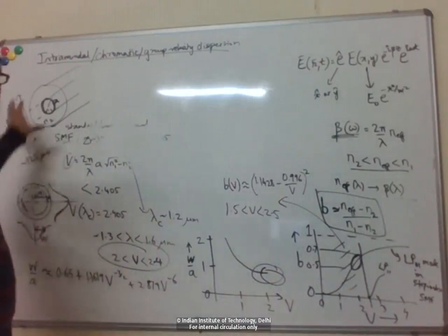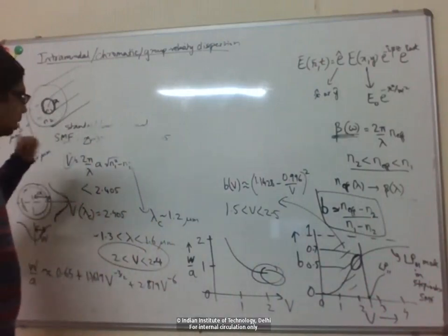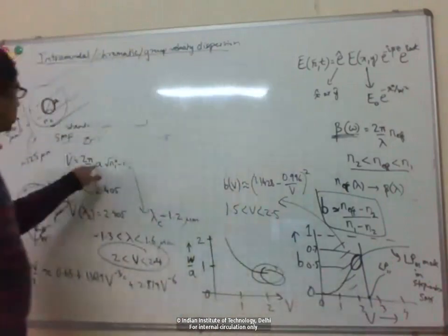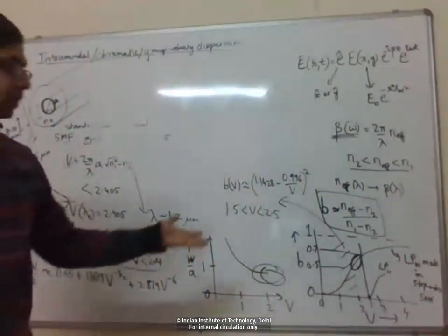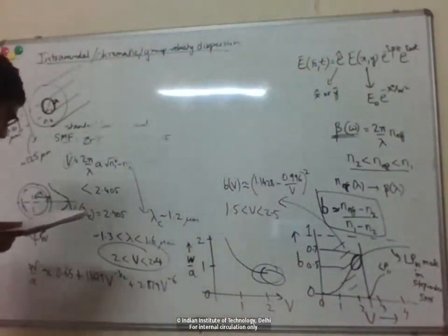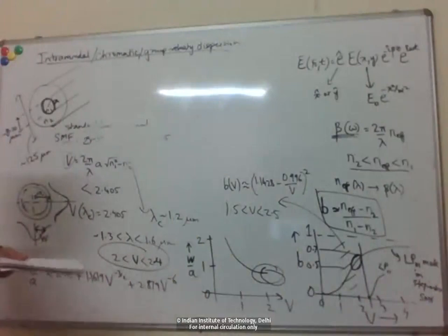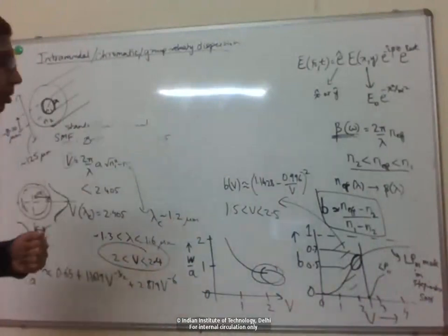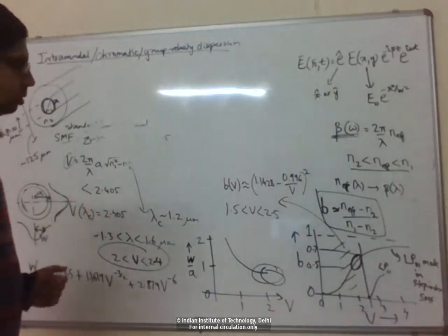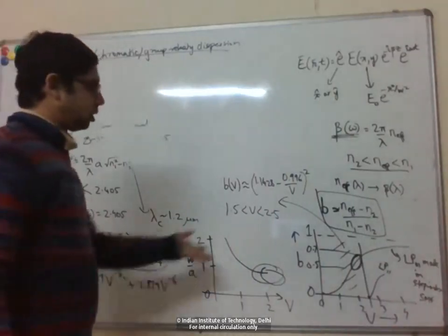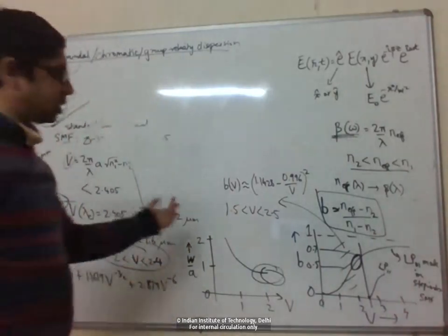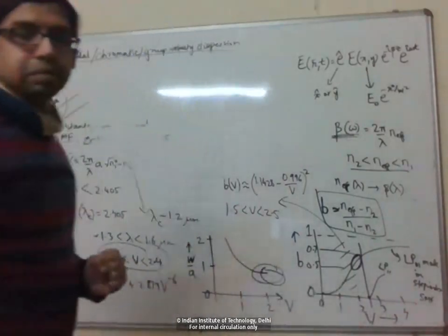Whatever the case, as long as you have a step index fiber, the propagation constant just depends on the V number, not on the individual values. That's convenient because we can use the same results for all the fibers just from the V number.